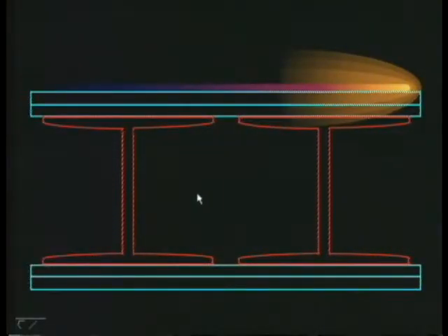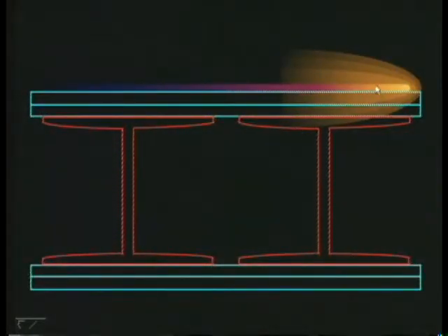Yes. Now take a look at this. Here you see a single I section with plates is not sufficient. Then you can choose 2 I sections placed side by side and join them with the help of plates. Joining, in the sense, in the next class we will be dealing with the riveted joints. There we will see how to design a riveted joint. Here you can have rivets like this, or you can also go in for welding.